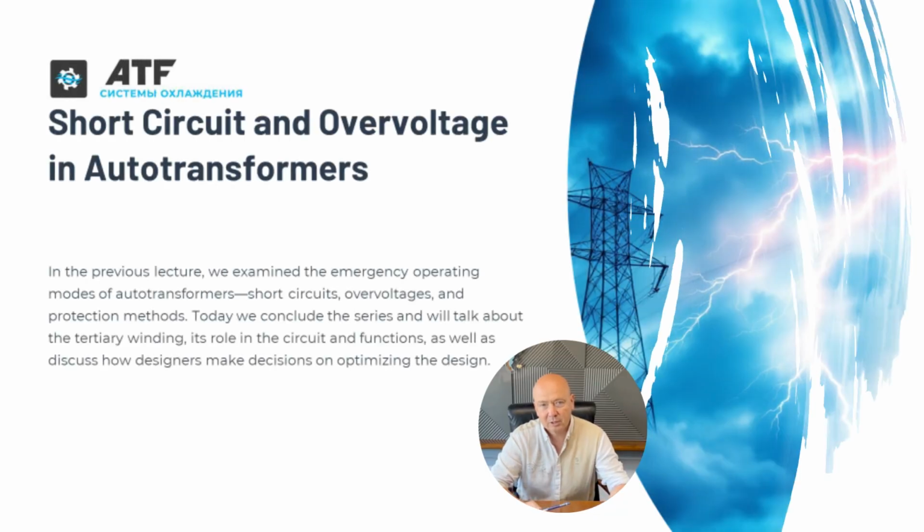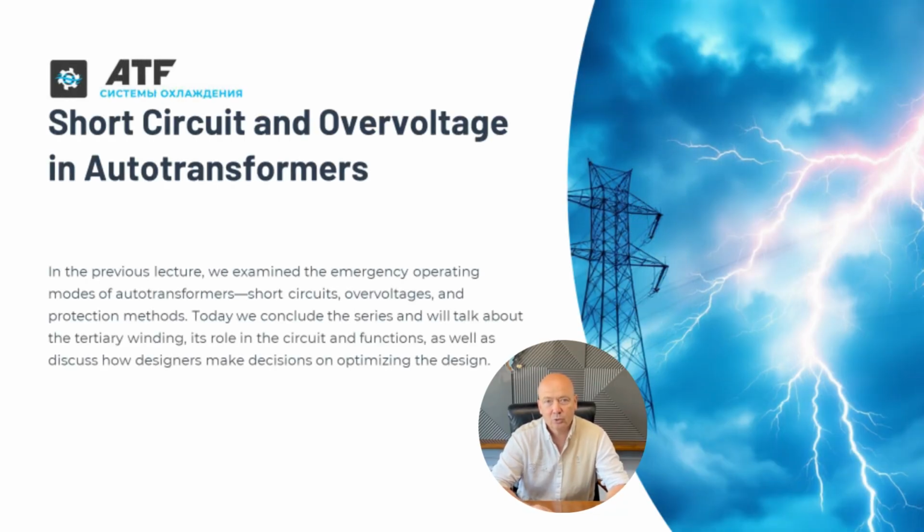In the previous video, we discussed emergency operating modes of autotransformers, short circuits, overvoltages, and protection methods. Today we are completing this series and will talk about the tertiary winding. We will explain its role in the circuit, its functions, and the conditions when it can be omitted. We will also examine how designers make decisions on structural optimization, balancing cost, weight, and reliability.